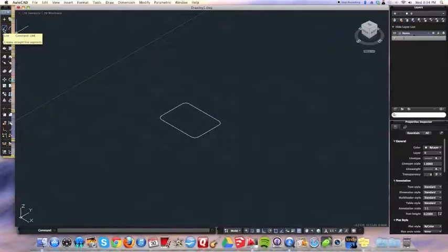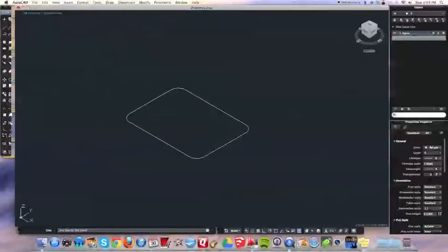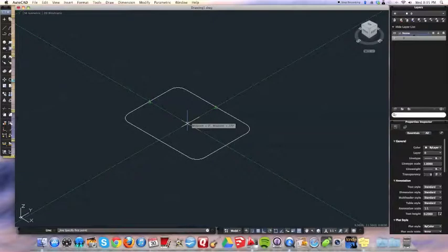I'm going to erase it later because I won't really need it as part of the drawing, but just as a reference. So first thing, I need a line, and I want it to be directly in the center here, which I could probably count squares and measure it out, but since I have object snap tracking on, I'm going to hover on the midpoint there, hover on the midpoint there, and move until both of them light up. Sometimes you have to really wait a minute until that activates. There we go. I'm going to click here, and then I'm going to start drawing up.